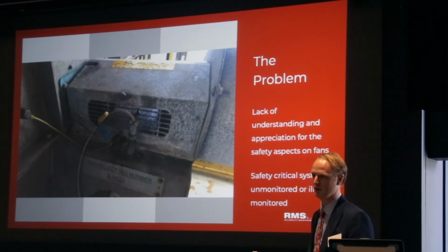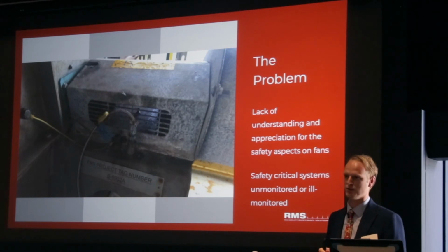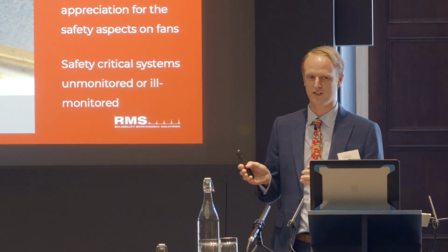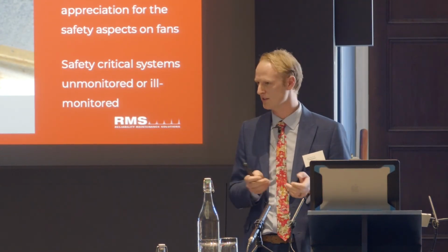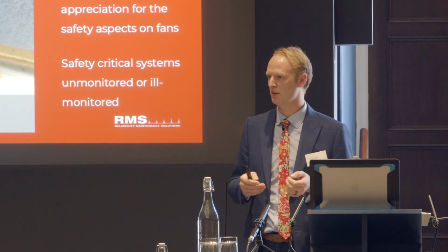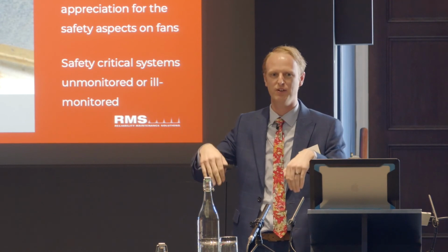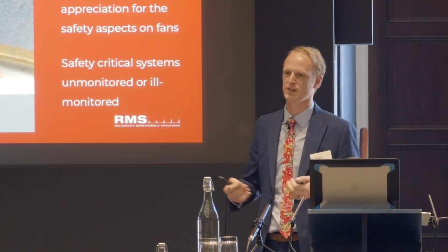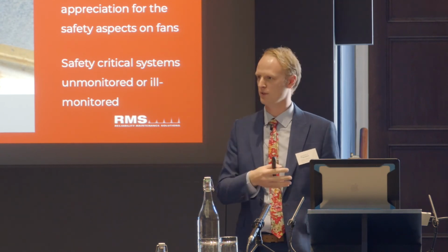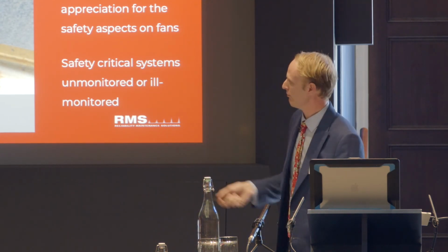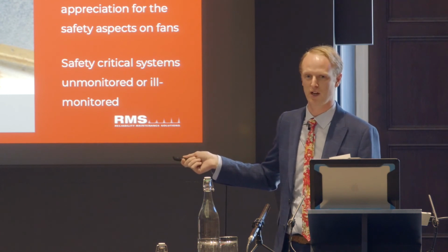So you can shout out the answer, but where do you think the degree of movement is greatest on this fan? Not vertically, no. So we've got gravity pushing down. If vibration increases on the fan, it's most likely to be in the vertical domain, so on that plane. So it's no good being vertical for a start.